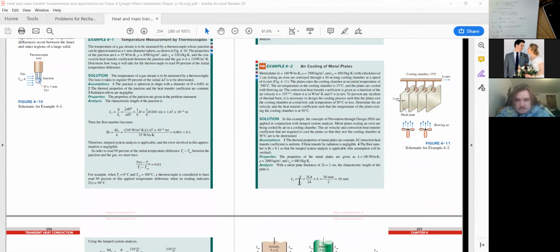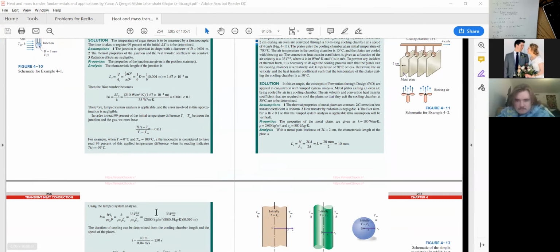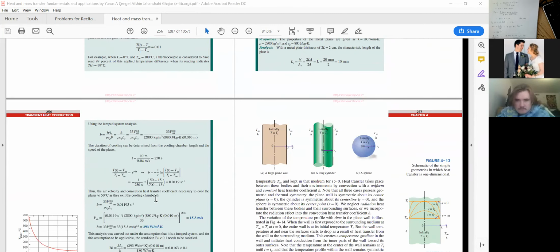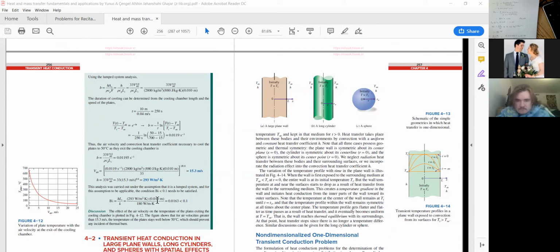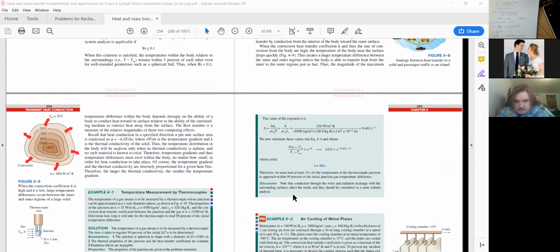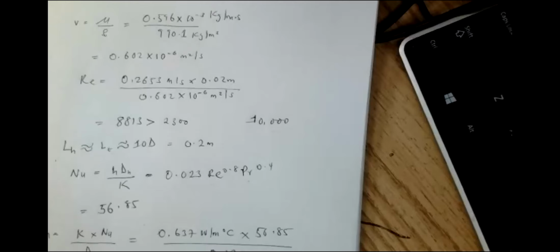Then you do the test by making this analysis. So you have 2L equal to 2 cm. You find your value of L, and then you put it in the Biot equation just to find if the value is less than 0.1. If it is less than 0.1, then you can go ahead and use this method. So once again, sorry that I made a mistake in the last class. I just wanted to make that correction.